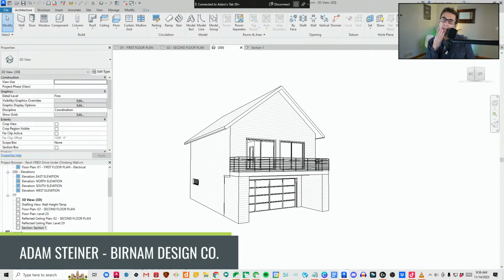Oh, no, sorry. I have done a handful of decks over floor area as well, which we did with EPDM membrane. You build the structure for the deck, EPDM membrane, and then tapered sleepers that the decking sits on. So, yeah, one of those options.